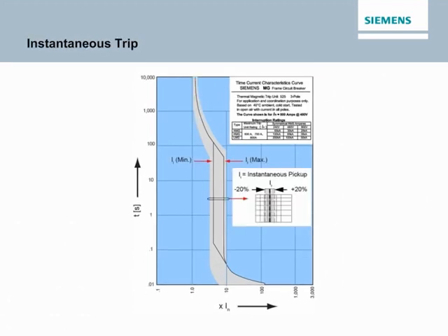The middle and bottom parts of this time current curve show the instantaneous trip performance of the circuit breaker. Note that the maximum clearing time, which is the time it takes for the breaker to completely open, decreases as current increases. This is because of the high-speed contact designs which utilize the magnetic field built up around the contacts. As current increases, the magnetic field strength increases, which speeds the opening of the contacts.